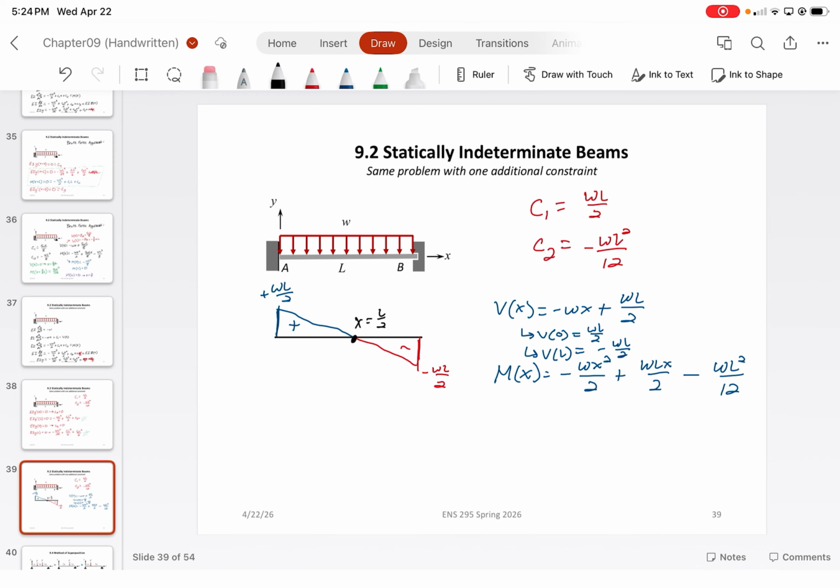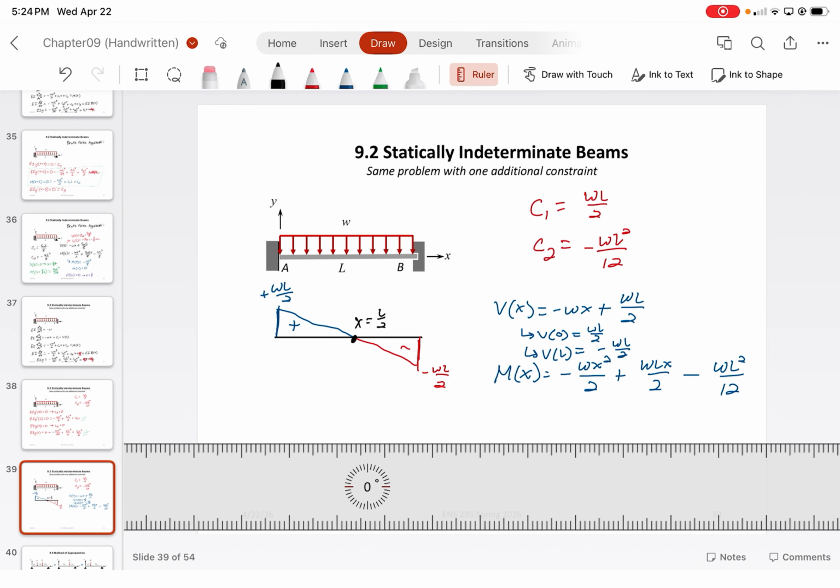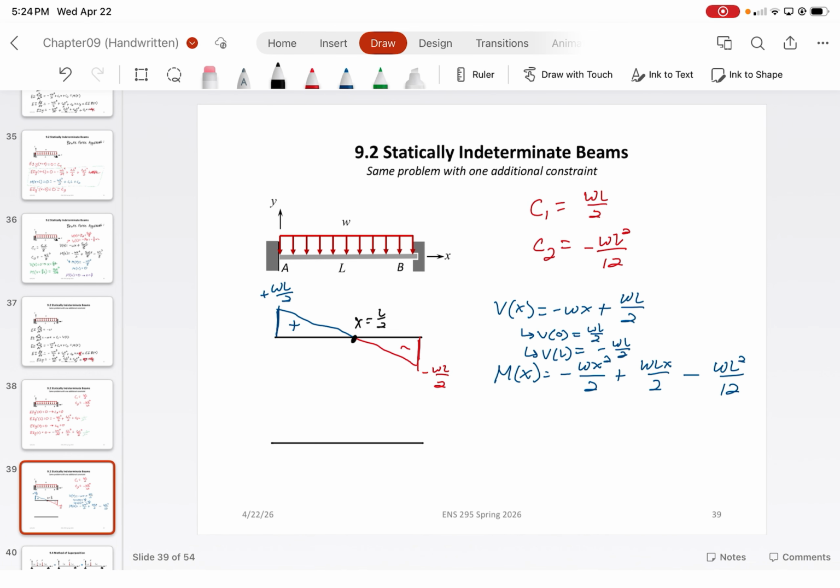But what about the bending moment diagram? How is that going to look? What do you guys think are some important points that we would want to know? The crossing point. Yeah. What do you mean crossing point? Like the inflection? The 0. That's just going to be the midpoint. Yeah. But I would say, generally speaking, we just want to know more so about the design values. So that would be like, what are the maximum and minimum locations? Because we could figure out everything else from there.